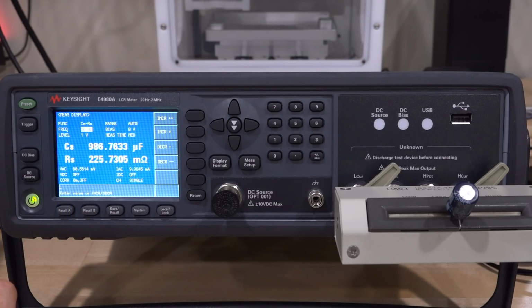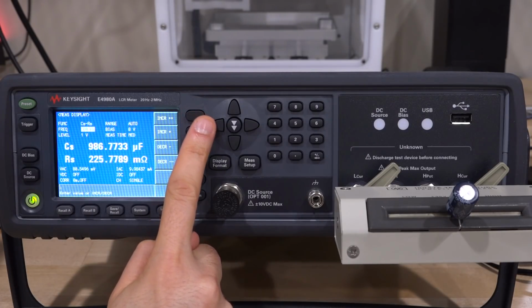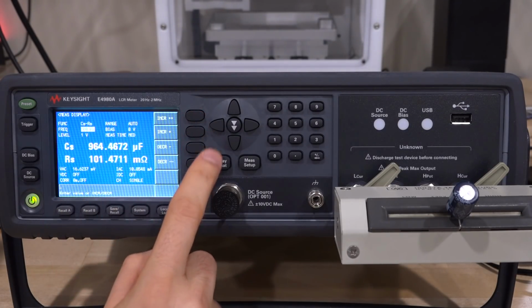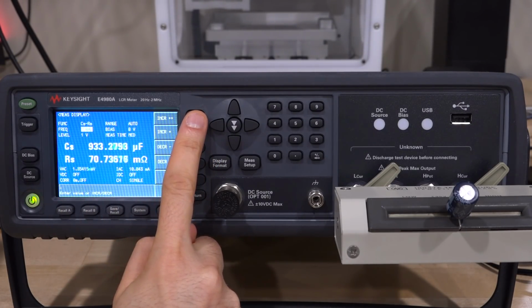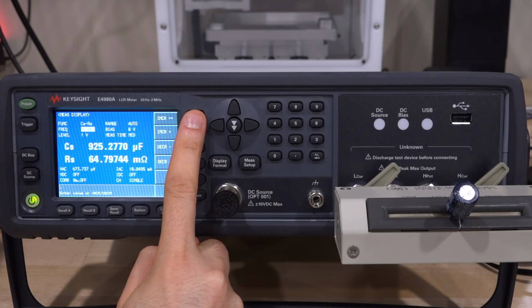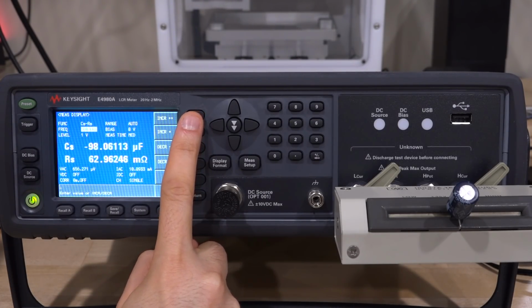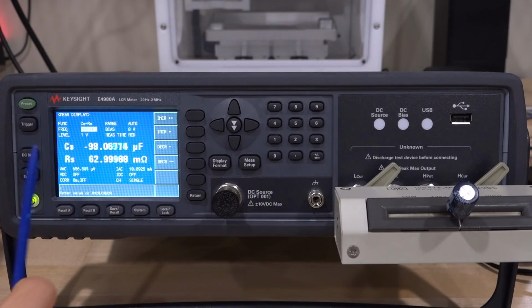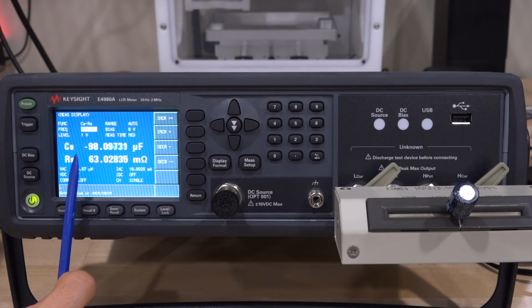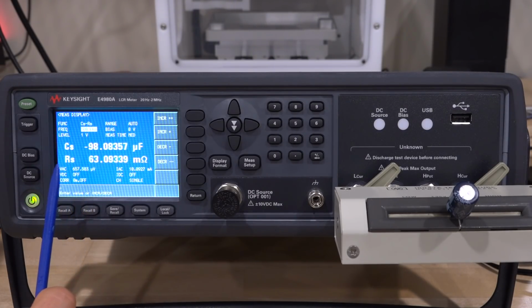at 20 hertz. Let's now increase the frequency from 20 hertz to, let's say, 100. You can see the capacitance already beginning to change. Let's go to 1 kilohertz. Now it's really beginning to change. 10 kilohertz, now it's lower. And as soon as I hit 100 kilohertz, of course, we are now past its self-resonance. We're measuring a negative value, and that negative value means it is now an inductor. So we're beyond the frequency for which this capacitor is even a capacitor at all. That's because all the inductances and capacitances are interacting and eventually passing the resonance.